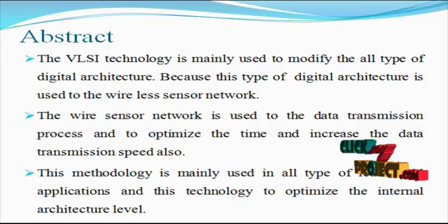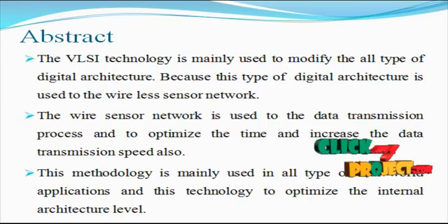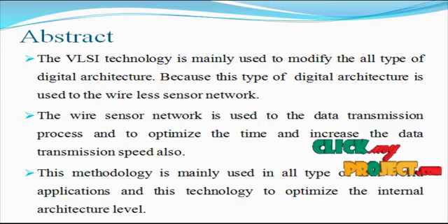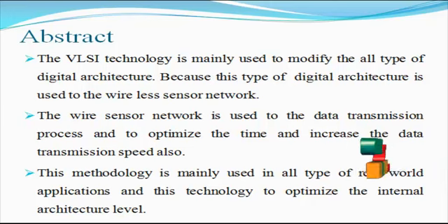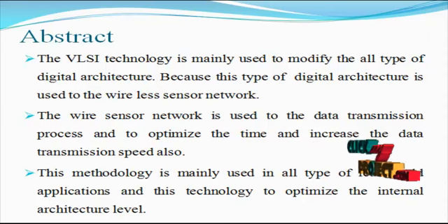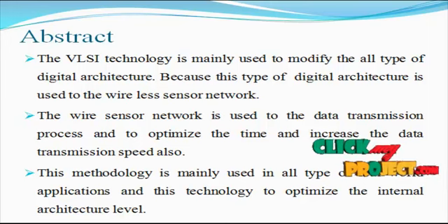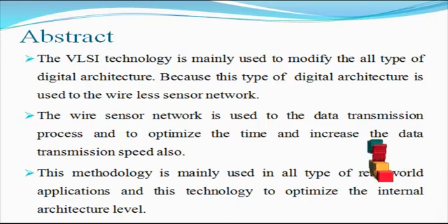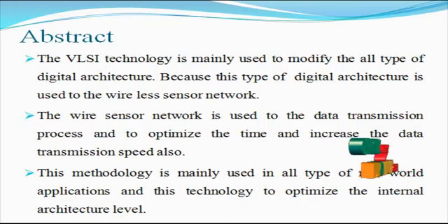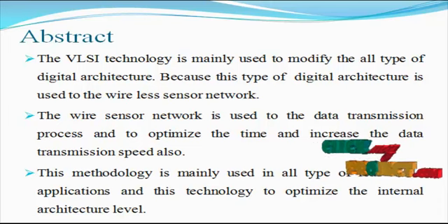Radio communication exhibits the highest energy consumption in wireless sensor nodes, given their limited energy supply from batteries and scavenging. These nodes must trade data communication for on-node computation. Currently, they are designed around off-the-shelf low power microcontrollers, but by employing a more appropriate processing element, the energy consumption can be significantly reduced. This paper describes the design and implementation of a newly proposed folded tree architecture for on-the-node data processing in wireless sensor networks using the parallel prefix operation and data locality in our hardware architecture.